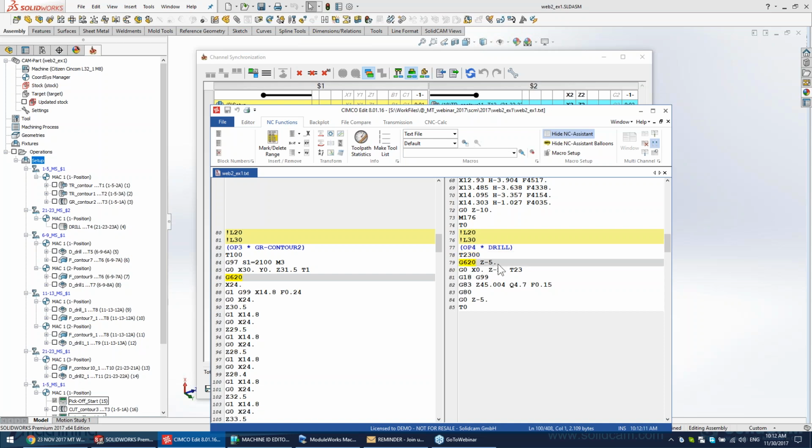With superimposition command, I will bring the tool close to the part, 5 millimeters distance from the part, and going to the first position in the tool path with the offset, having the canned cycle G83 to drill. Here we have the grooving tool path.